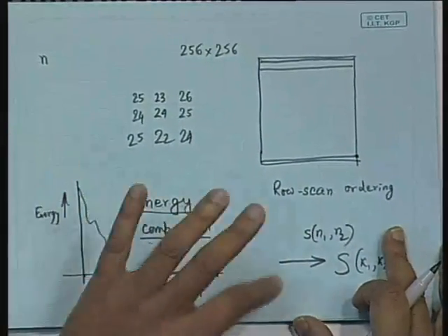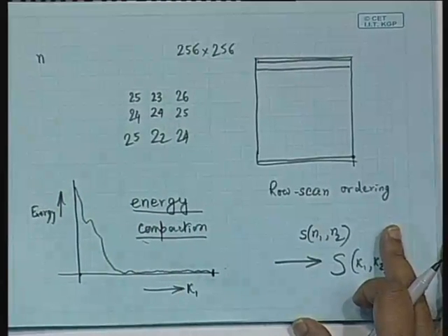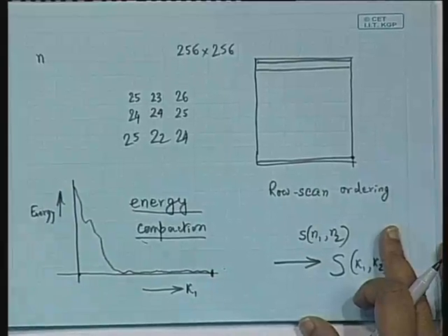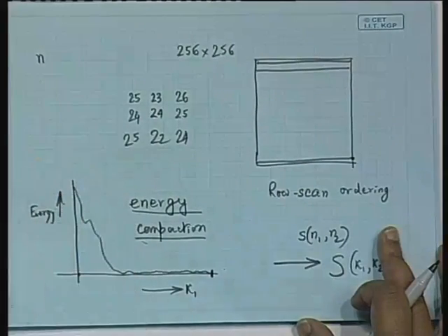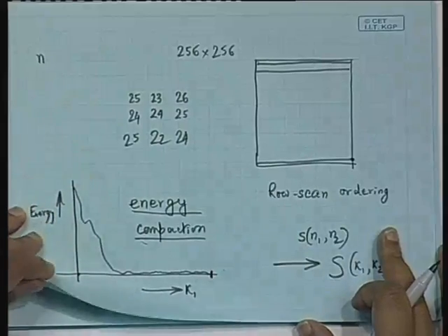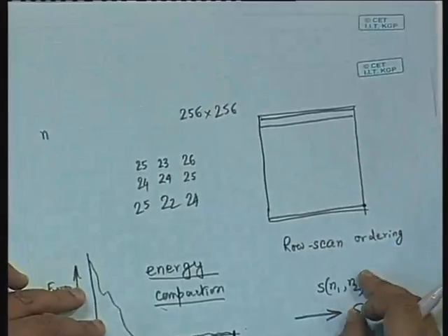We could not get this picture in the original spatial domain, but we can get it after studying the redundancy that is present in the original picture domain, and the redundancy is best depicted in the transformed space. While carrying out the transformed space analysis, we will find that there is an energy compaction, and that energy compaction essentially leads to the fact that we can achieve a good amount of compression if we first use the transformation followed by a quantization.